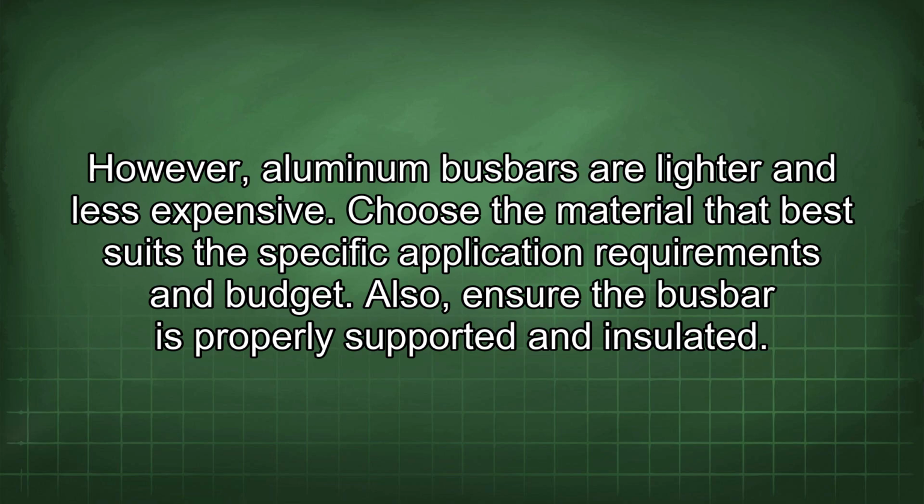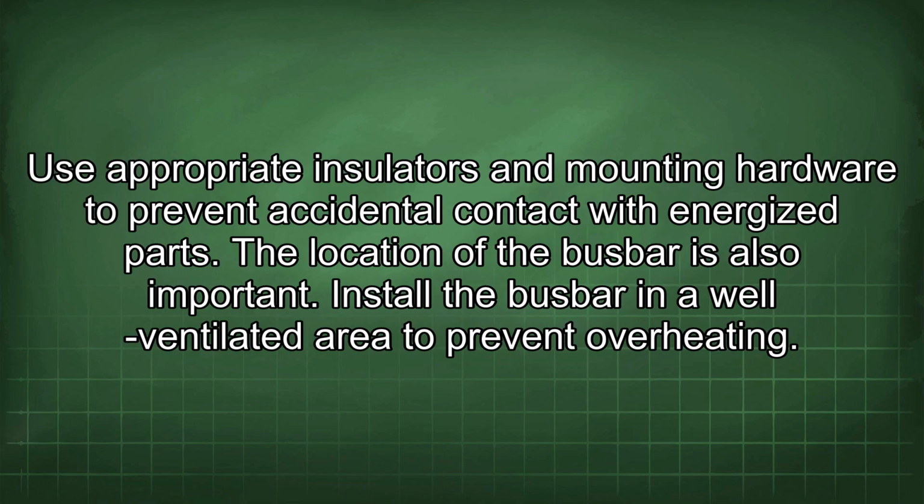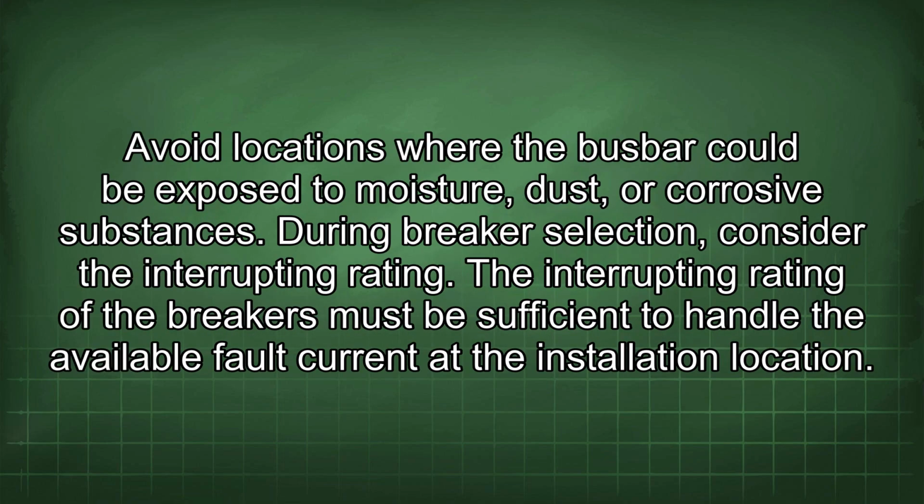Also, ensure the busbar is properly supported and insulated. Use appropriate insulators and mounting hardware to prevent accidental contact with energized parts. The location of the busbar is also important. Install the busbar in a well-ventilated area to prevent overheating. Avoid locations where the busbar could be exposed to moisture, dust, or corrosive substances.